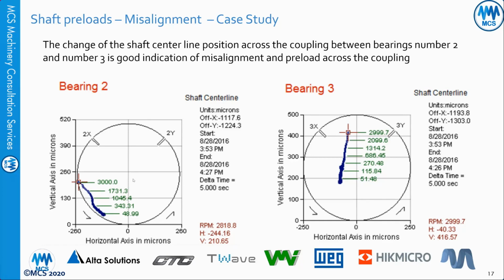If we talk about the stiffness, the shaft stiffness plus the bearing stiffness, both together, will increase the total stiffness. And when the shaft is running very near to the bearing internal wall, it will drag some oil with it, and it will squeeze this oil at a certain position, creating the oil wedge, which will act something like a pillow carrying the shaft.